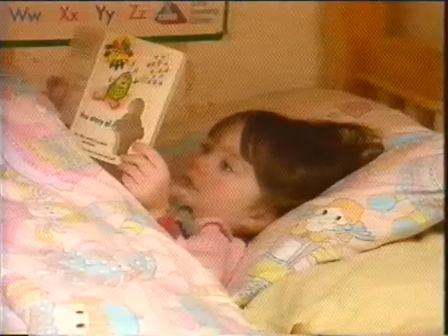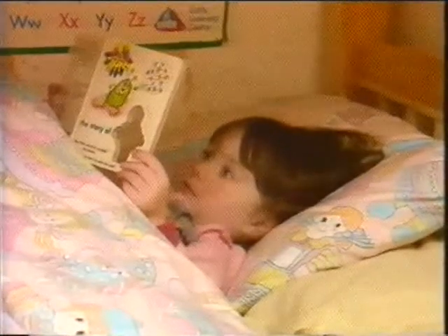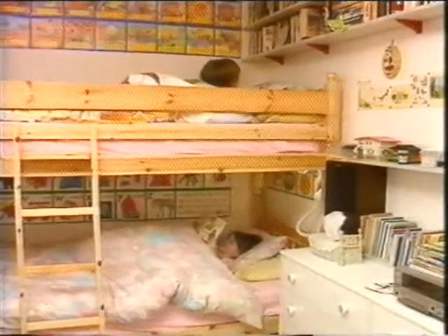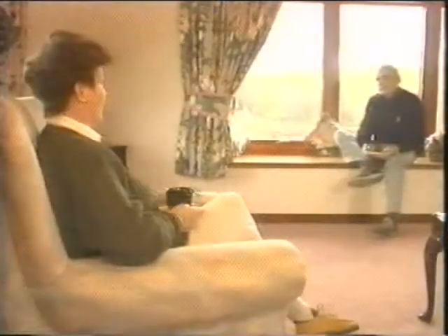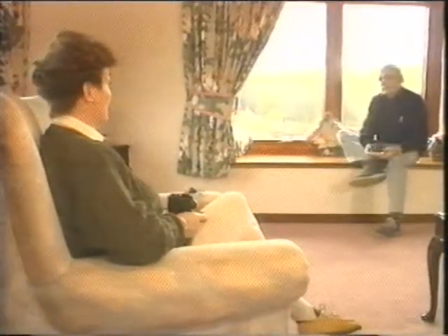The temperature needed in a bathroom, for example, is higher because there's less activity there, people are probably not wearing as much, and the air needs to be changed more frequently. In a bedroom, on the other hand, there's not much activity, but people are under duvets or blankets, and so the temperature can be lower and there are fewer air changes. So when we're designing a system, we have to think about these differences.